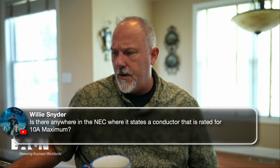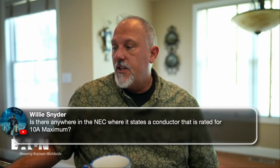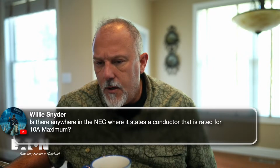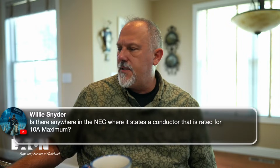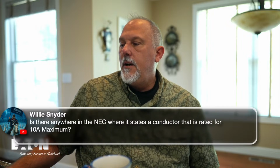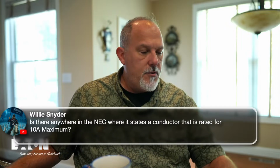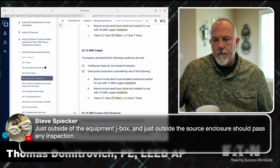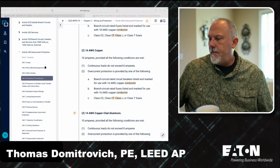240.4. If I look at 240.4, there's small conductors in D. So what this tells you is, so your question was, is there anywhere in the NEC where it states a conductor that is rated for 10 amps max? Here's how I interpret it. Let me close this out.